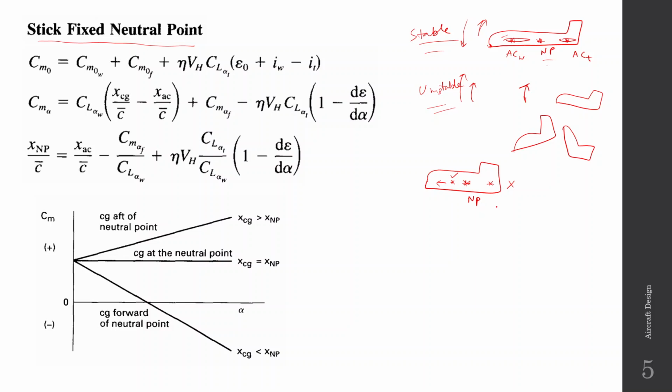But it is not desirable to make the aircraft too stable because then it is difficult to intentionally change its orientation. Let us say we want to change the angle of attack intentionally, then that becomes difficult. It requires a lot of control effort. You will require larger elevators and control surfaces to produce that effect. So too much stability is also not good.